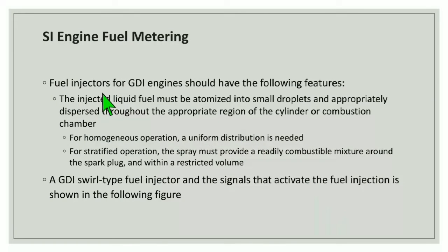GDI engines should have the following features. The injected liquid fuel must be atomized into small droplets and appropriately dispersed throughout the appropriate region of the cylinder or combustion chamber. For homogeneous operation, a uniform distribution is needed, and for stratified operation, the spray must provide a readily combustible mixture around the spark plug and within a restricted volume.